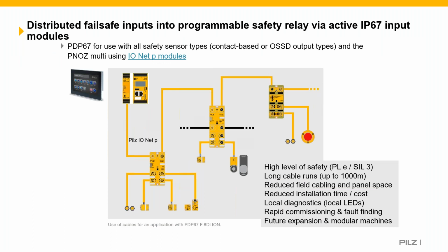Alternatively, you can connect distributed fail-safe inputs into programmable safety relays, such as a PNOZ multi 2, via active IP67 input modules. So these PDP67 modules can be used with all safety sensor types, contact-based or OSSDs, and the PNOZ multi using